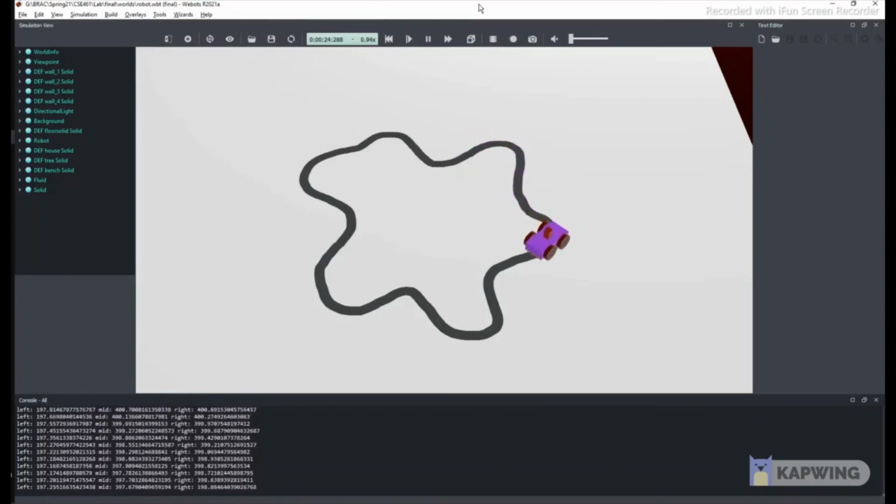Similarly, when making right turns, the right sensor and the middle sensor give a high reading, whereas the left sensor gives us a low reading. This causes the right motors to stop working and the left motors to speed up. This causes the bot to make a right turn.